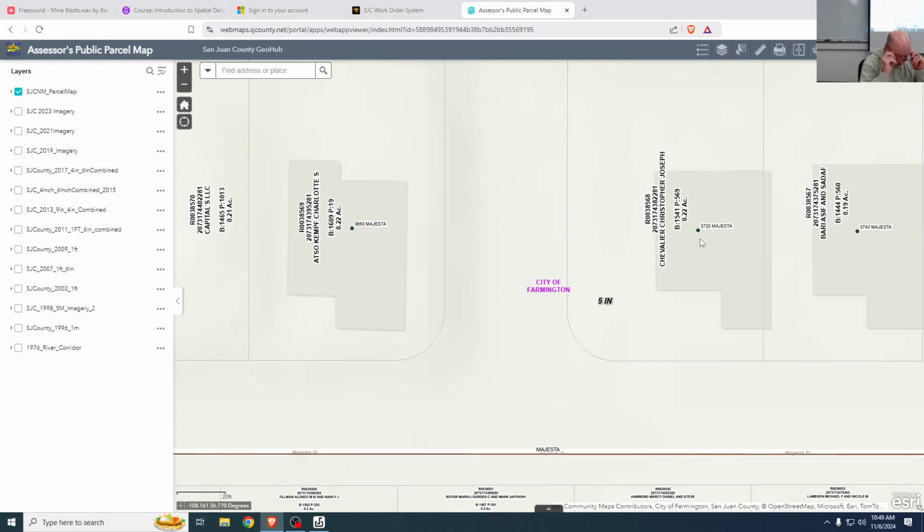So a full legal description would include, depending on how it's written, usually the shorter, smaller stuff first. Like lot number 4 and block number 1, and then the subdivision name, and then the township or the section number or the quarter section, depending on how that subdivision was blocked out.